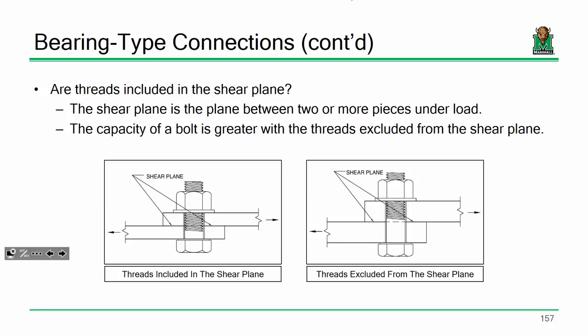Okay, to answer your question, yes, it would be advantageous, but sometimes it's not so simple, because it's going to depend not only on the availability of the bolt. Let's say I choose a 3/4 inch diameter bolt. Well, 3/4 inch diameter bolts are available in various lengths. So I might get a 2-inch long bolt, a 3-inch long bolt. So that's one parameter. Another parameter is the thickness. Is this 5/8 inches thick? Is it 3/4? Is this a 1/2 inch?